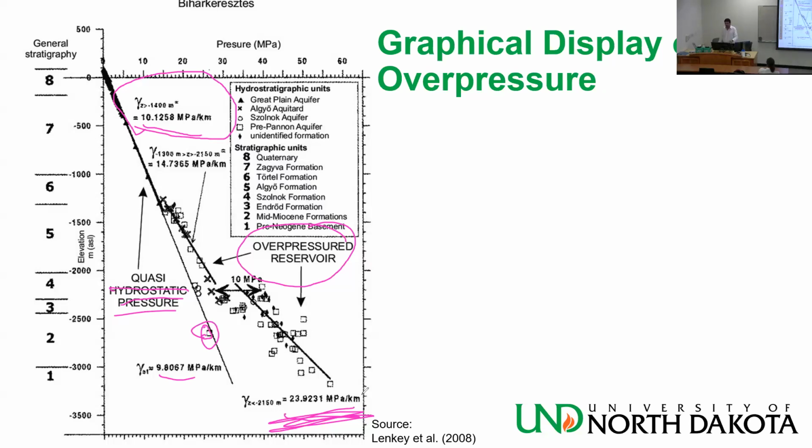That tells me that the lithostatic in these areas is actually higher than 1 psi per foot, because there is no chance you can have this pore pressure without lifting the earth. If SV was 1 psi per foot, which is 23, and pore pressure was more than that, it means that you are lifting the overburden. You are lifting the rock off the ground.